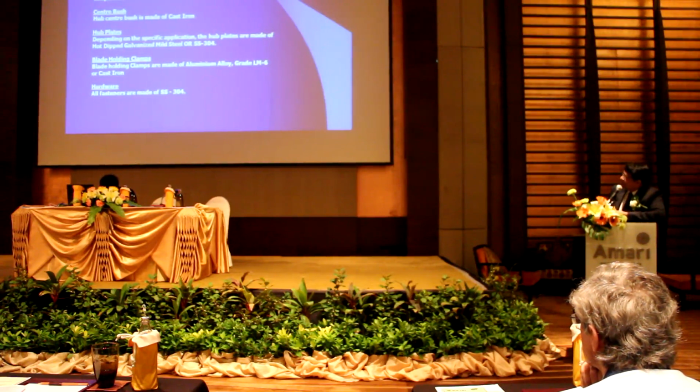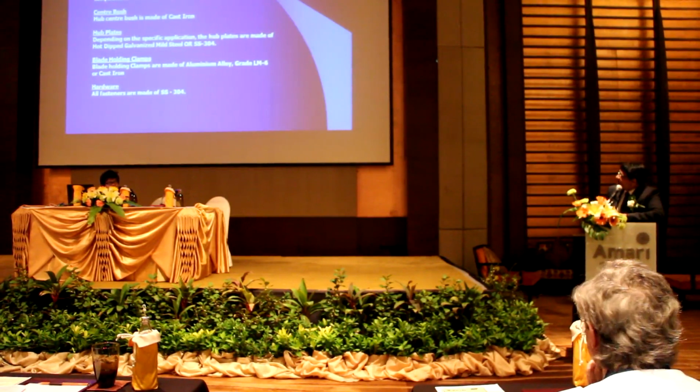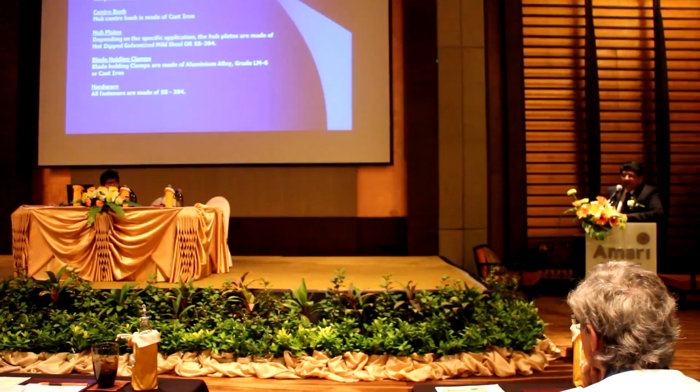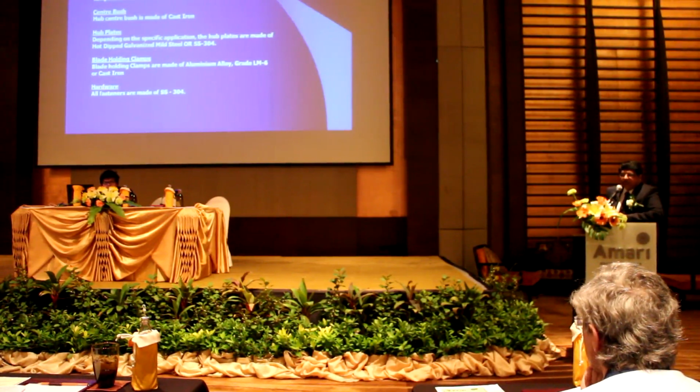The hub plates, we have been giving even stainless steel 304 or stainless steel 316, depending on their requirement in the environment for corrosion purposes. The clamps usually are given aluminum alloy, LM6 or cast iron. The hardware, as a design choice, we give them all SS304 stainless steel.